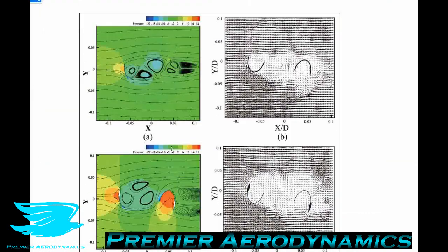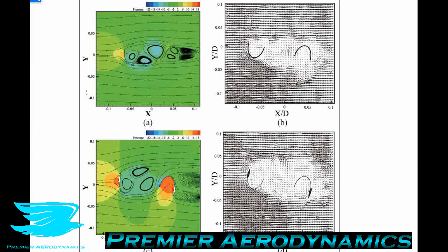Okay, so the top ones are for the blades without the airfoil profiles. The bottom ones are with the airfoils. For the blades that only produce drag, these top ones, the flow physics is very different. First of all, the pressure distribution is fairly uniform, hovering at around 0 pascals gauge. So you can see it's mostly green with a little bit of blue and a little bit of red.